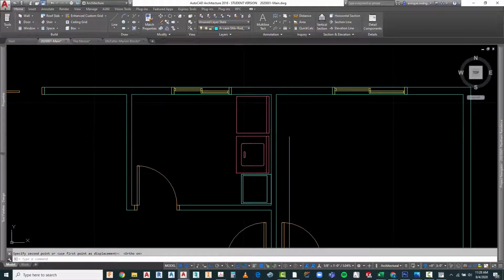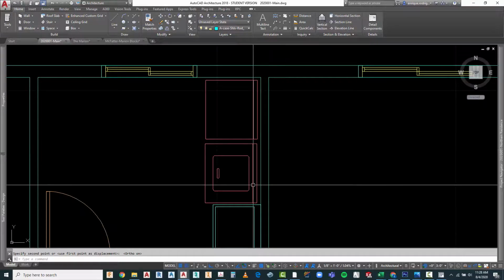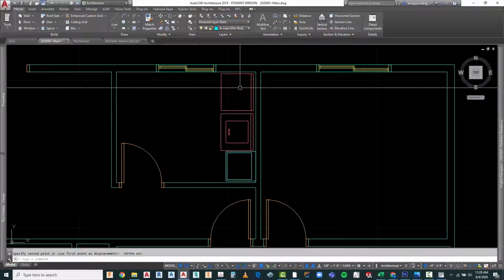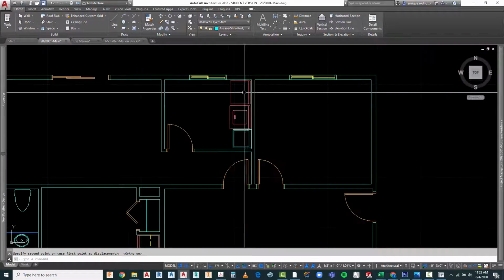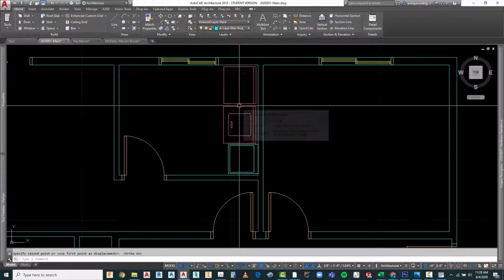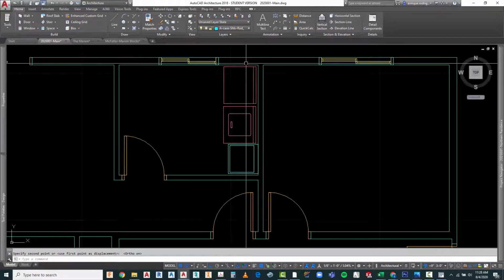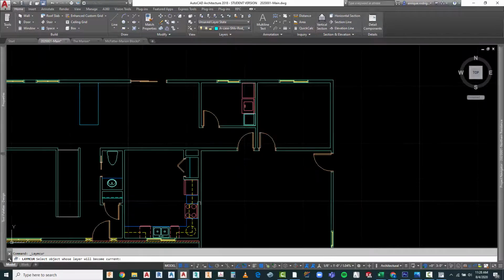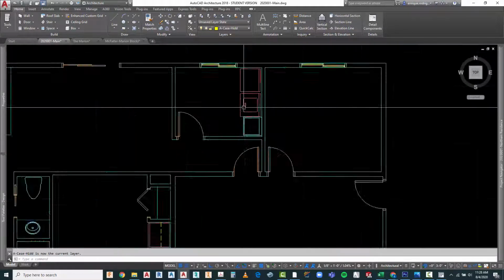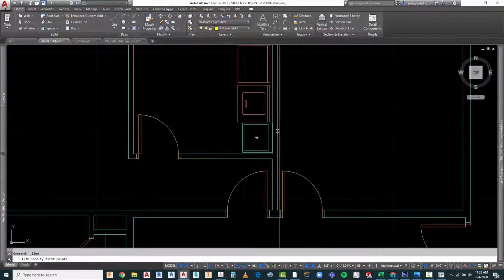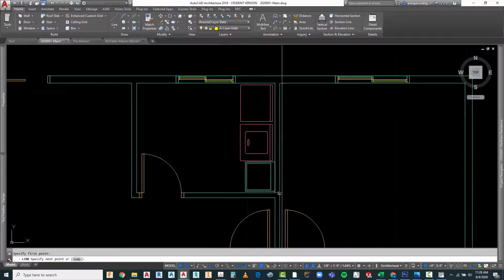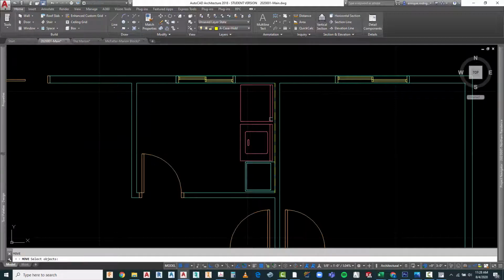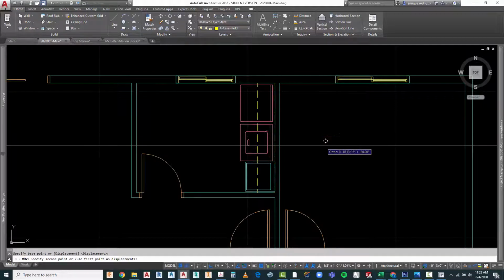Now this also shows either some upper cabinetry up into here, or some kind of a shelving. So I'm going to assume that we're going to do some cabinetry work across the top, and I'm going to carry it all the way across here. I want to make sure I'm in the right layer. I'm going to use this for A case, and in this case I'm going to go ahead and draw it here and move it over 12 inches to the left.